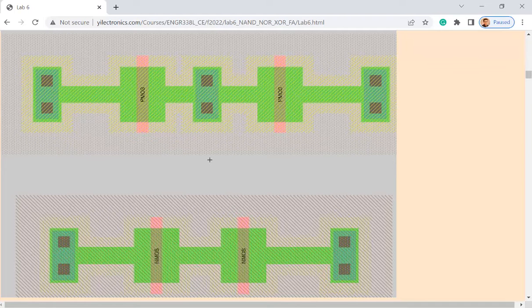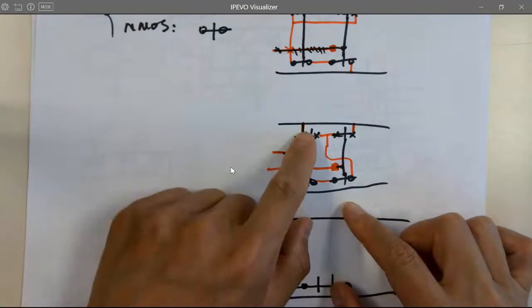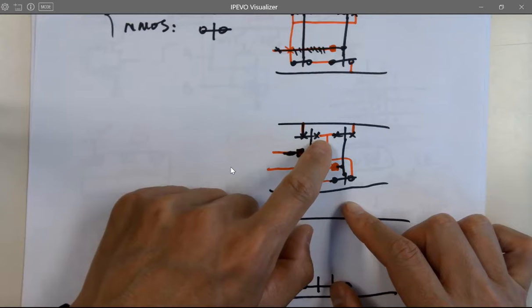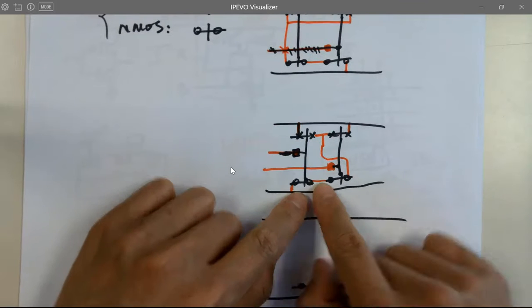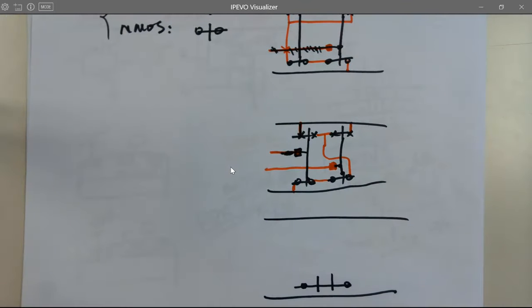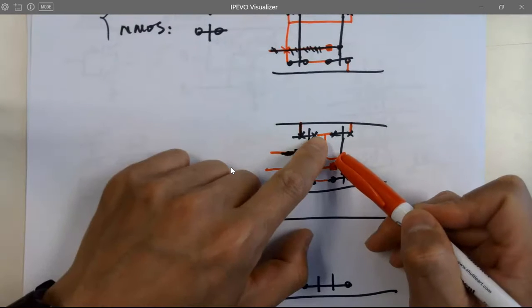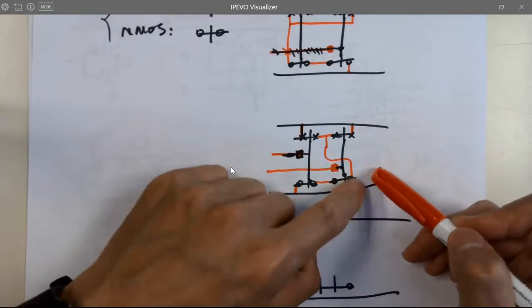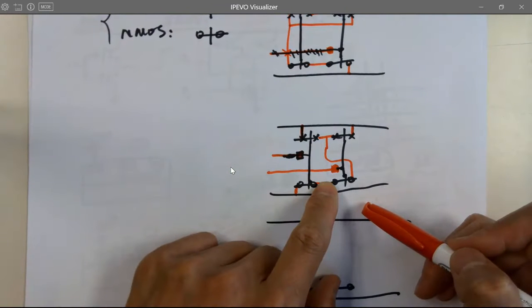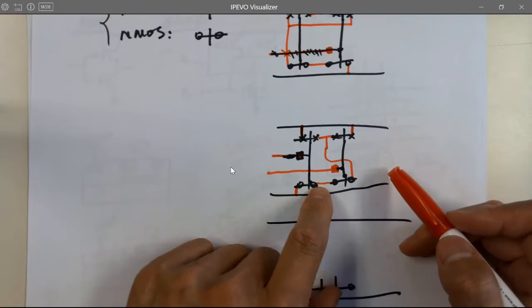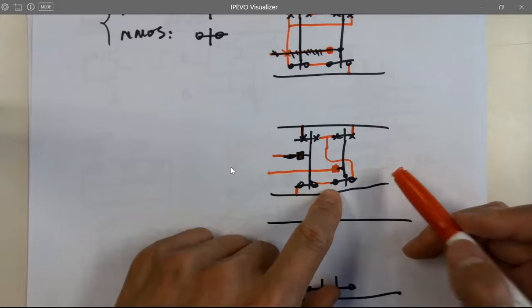Yeah, that's right. Yeah, because you need to introduce a wire in the middle. You need to introduce something in the middle on the metal 1 layer. Here, you don't need to introduce anything here, right? It's just something internally, right? Since you need to connect it to somewhere else, that's why you need a via in there to connect to metal 1. Here, there's nothing to be connected to the middle here. That's why I just directly ignore it. So whenever in the future you're not using any of the 2 nodes, you can directly ignore it or delete it.